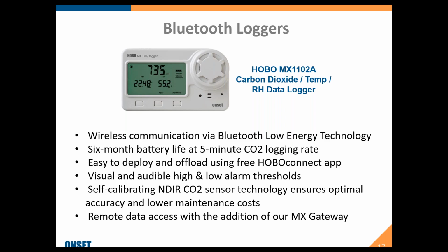Before this webinar, we did have the question of how does that work? How does the calibration on that sensor work? This logger offers not only a manual calibration up front, but it offers an auto calibration in the future. So initially what you'll do is you'll configure the logger, you'll place it outside for about 5-10 minutes, let it acclimate, hit the calibrate button. It goes through a process about five minutes, and then after that, you're good to go. You're good to put it in its place. What it's doing is it's taking that fresh air and setting what that logger sees to 400 ppm.